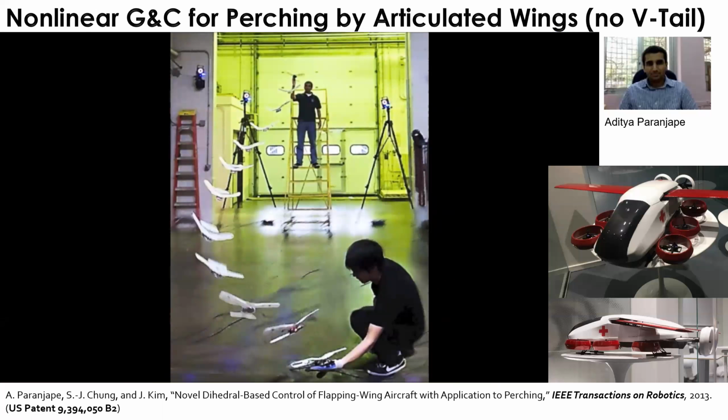Another extension: when I talked about Neural Swarm and Neural Lander, we were basically talking about offline training. You collect a lot of data, and then you can estimate the additional force coming from interaction with neighboring drones, downwash, or environment effects like flying close to a wall or to the ground.